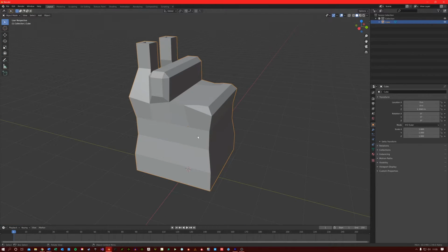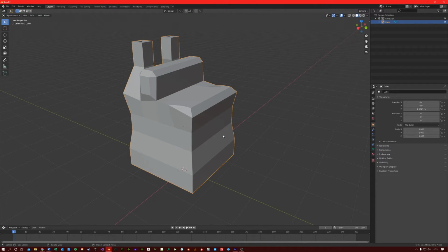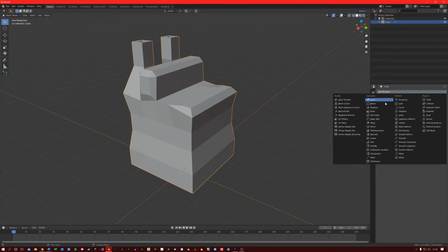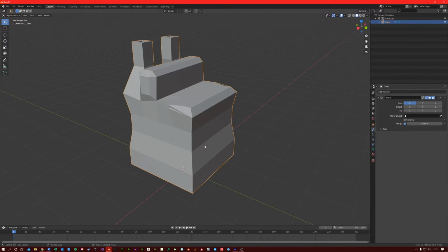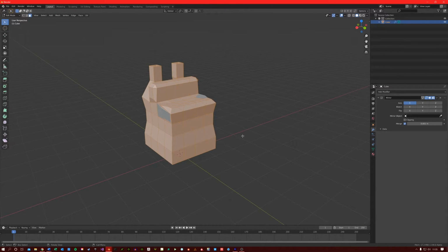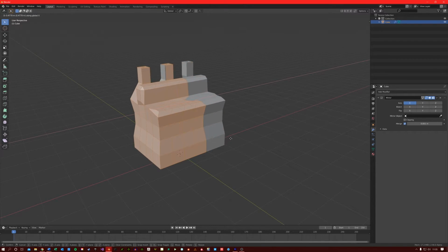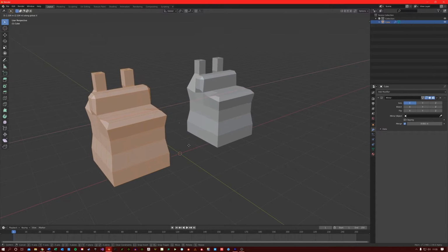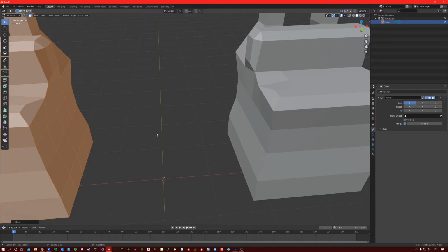So how is this important for the mirror modifier? Well, I will demonstrate that now. I'm going to add a mirror modifier to this mesh. As you can see, nothing has really happened because the mirror modifier is trying to calculate based on the local axes of the mesh, which is this point of origin here. If I now go into edit mode again and move the mesh whilst the mirror modifier is active, you can see that the object is now being mirrored with this point of origin, this orange dot here, being the center of this operation.